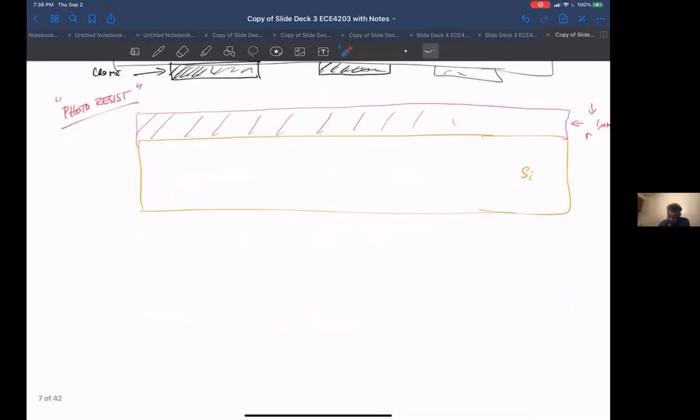And so say for a 65 nanometer process, you might have something like 50 plus masks to define all these different features. We'll see the steps you'll have to go through. And all of these masks might end up costing you, for a 65 nanometer process, $300,000 to $500,000.